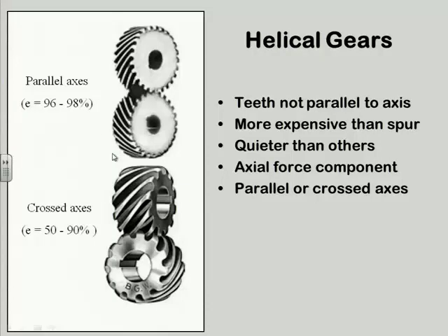Actually, some transmissions have helicals in reverse, too. I had one of those some years ago. It didn't whine going backwards, but it was harder to get into reverse. You had to muck with it. Had to put it in second first, and then to lock the thing up, and then quickly put it back in reverse to get the helicals to engage. So that was the trade-off. I'm not sure why they bothered, because do you care if you make noise backing up? How often do you back up, right?